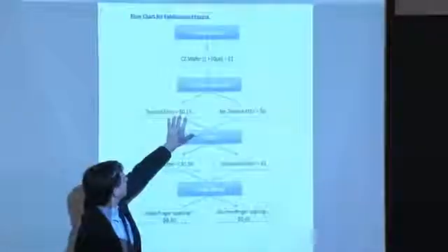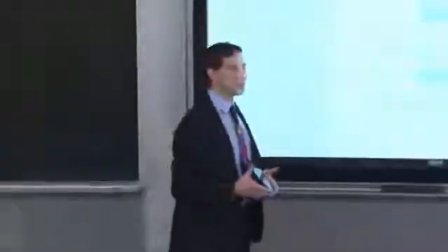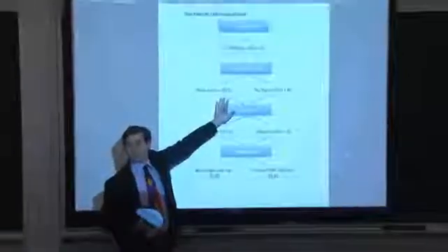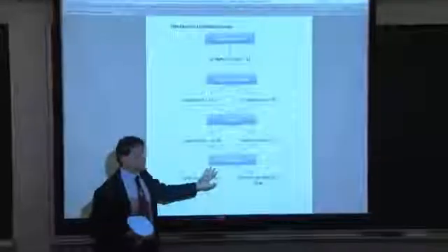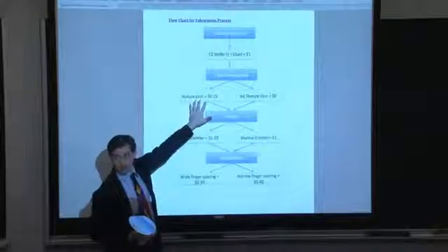You'll start with a wafer. It has a certain cost associated with it. You'll have some decisions to make concerning light management, whether you want to texture your front surface or whether you want to leave it bare and reflective, like this right here. Whether you want a reflective front surface or you want to texture it, there's a certain cost associated with it. So you can probably go to some online resource like PVCD-ROM and use their simulator or the one you've already constructed for homework number 2 and calculate what the predicted efficiency boost should be if you texture your front surface. Keep in mind, in this very simple solar cell here, we have no anti-reflection coating. So the texturization is pretty much all you've got for light management.